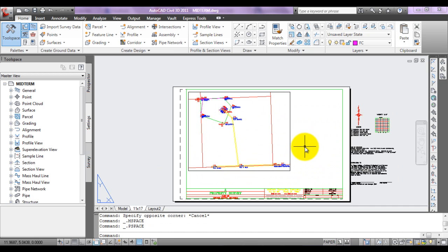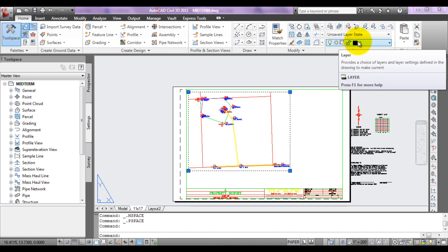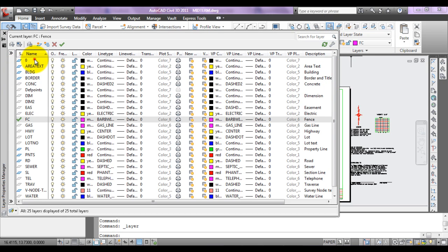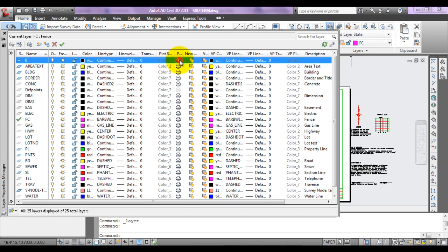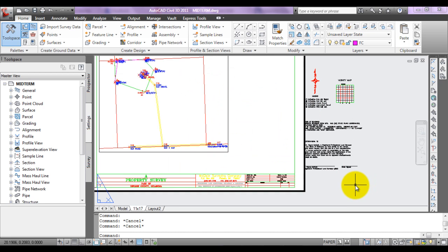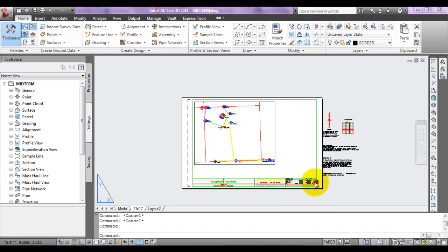So that's very handy. But what you can do is I select that layer, and I can see here that that is on layer 0. So what I'm going to do is I'm going to choose layer 0, and I'm going to say don't print layer 0. So that outer border will not print on layer 0. What's inside of it will, but that actual border of that viewport will not. At least I'm hoping. That's the way it has worked for me in the past, so I'm hoping that's the way it'll work for me again.